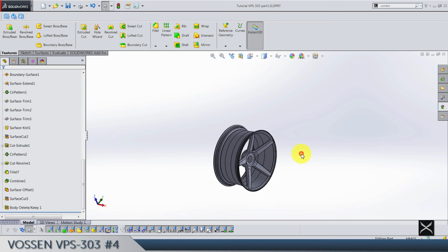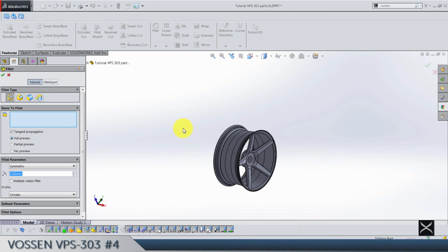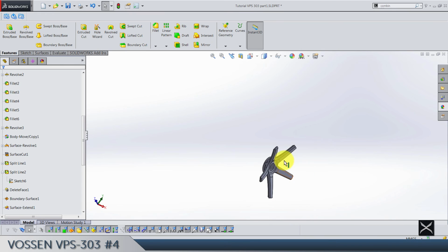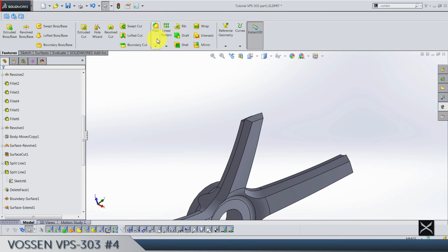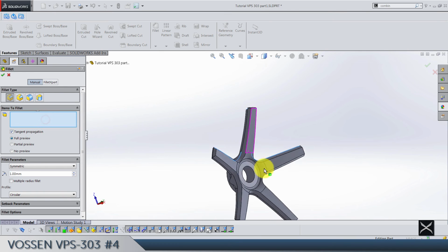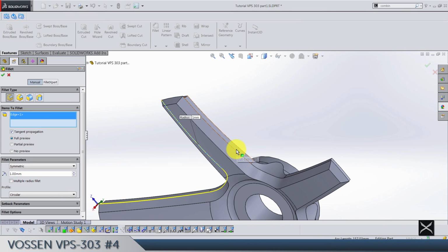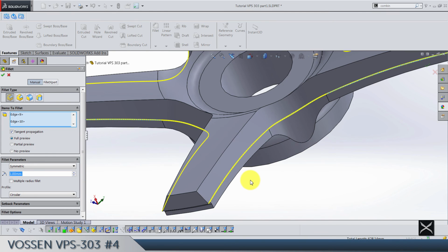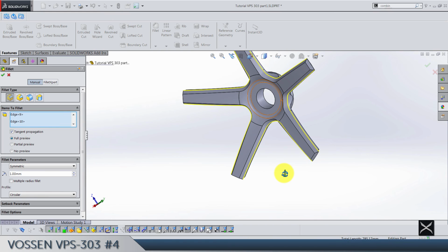And what's left is to, let me just check, is everything done. Yeah, we need to make one fillet, radius 1. Let's actually hide this profile to see this one easily. So make fillet 1 for this edge here. It's not working. Let's try again. I have to select all these 5 edges separately, and it's gonna be fine. So yeah, that's radius 1. Fillet is done.